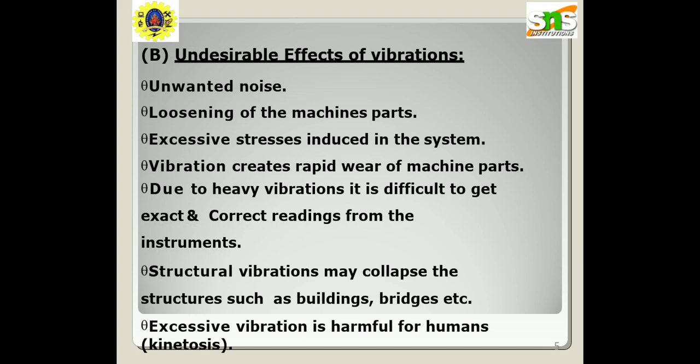The undesirable effects of vibration are unwanted noise, loosening of the machine parts, and excessive stresses induced in the system. Vibration creates rapid wear of machine parts. Due to heavy vibrations, it is difficult to get exact and correct readings from the instruments. Structural vibrations may collapse structures such as buildings, bridges, etc. Excessive vibration is harmful for humans.